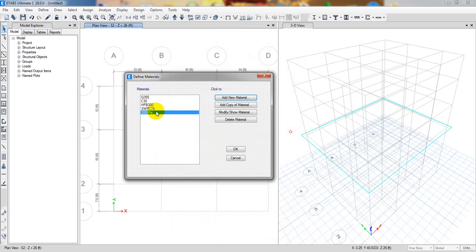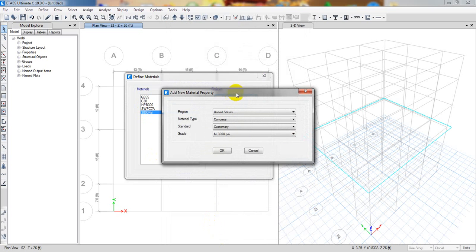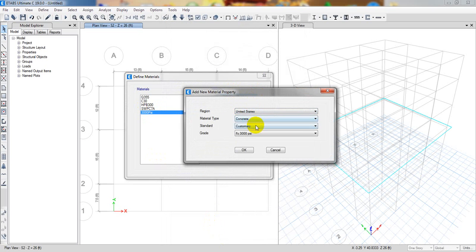So here are the rebar material properties, for our steel properties. United States, it's okay, and it's rebar. Obviously, here are the different grades: grade 40, 60, and 75. So I'll simply select grade 40. This is ASTM A615. As per that code, if you select that code, then here you only see grade 40, and you can use the user defined. So I'll just go here, rebar, and ASTM like that, and grade 60, then okay.